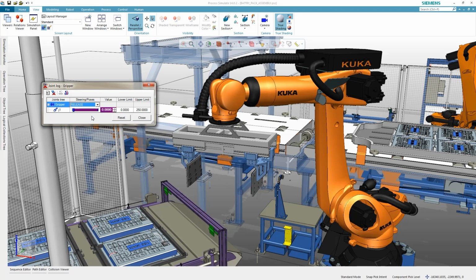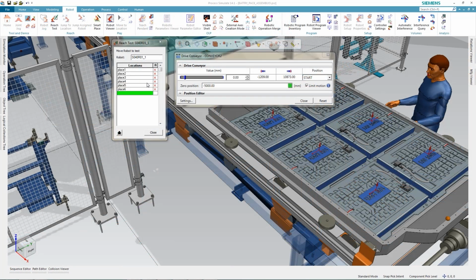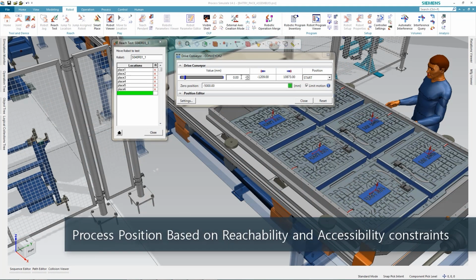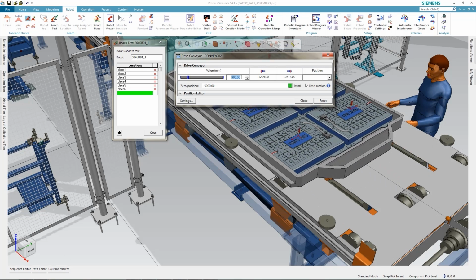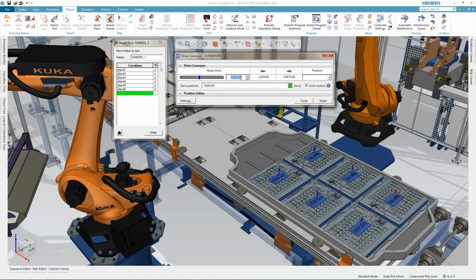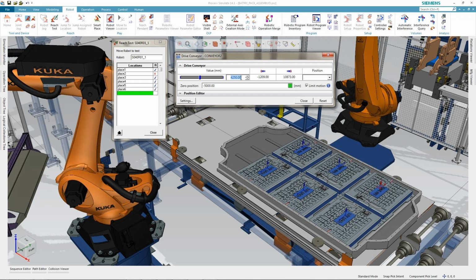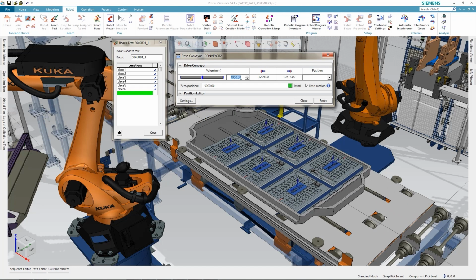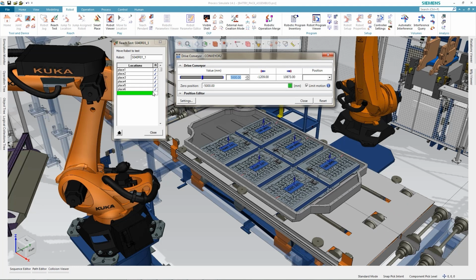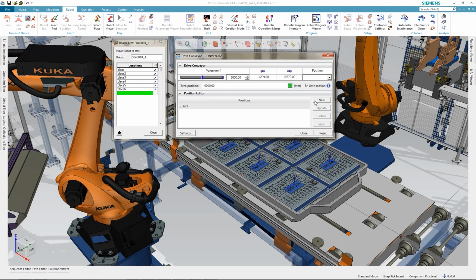By using Process Simulate analysis tools, the user can test and verify the robotic assembly process with regards to the geometric and kinematic constraints. In this example, it is desired to set the battery pack on the conveyor. Then, once both robots can reach all process locations, a sensor is created to detect the battery pack is in the right place. The system allows one to create proximity and light sensors to define the behavior, reflecting the behavior of parallel sensors existing on the shop floor. Such sensors are used to detect a part presence or absence, or to emulate the behavior of safety screens.